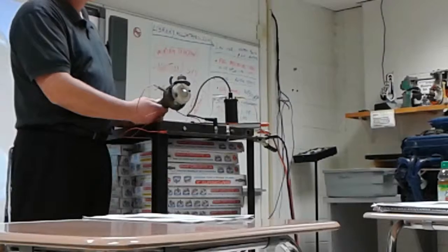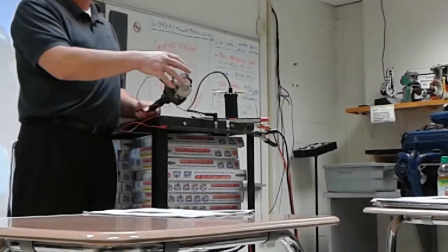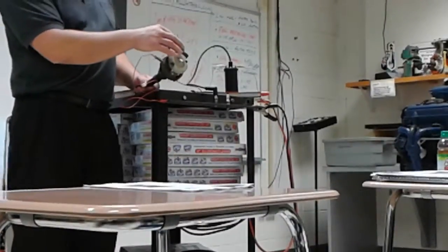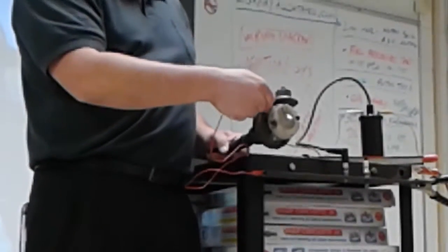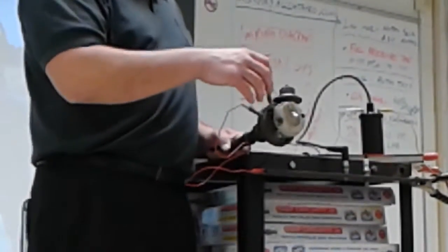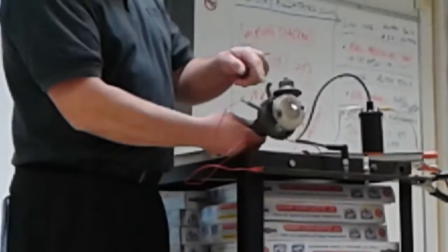Okay? Now in a car, we use a device like this that has the breaker points built into it, this device called the distributor. Your machine has it built into the flywheel, and that coil that you guys were always taking off and putting on, the magnet was always stuck to it. That is where this is all built in. Inside that little coil is where the switching system is, this breaker point system.